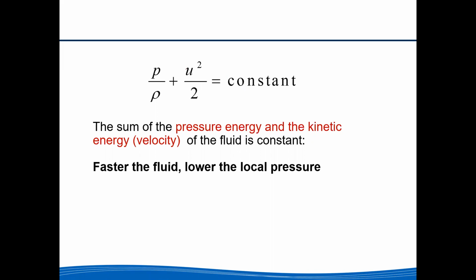In other words, the Bernoulli equation is a way to state that the sum of the pressure energy and the kinetic energy, the velocity of the fluid, is constant. Therefore, the total energy in an inviscid fluid is constant. Energy is not lost through the flow. And wherever the fluid is faster, higher U, the local pressure will be lower.